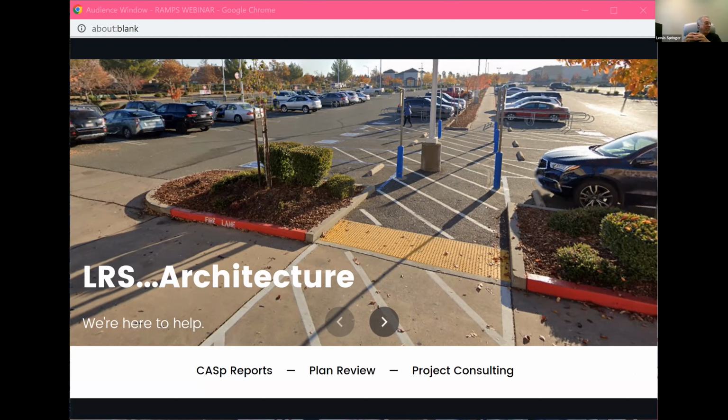But our first question is, could you please repeat the difference between blended transition and curb ramp? Okay, so what I like to look at is that a blended transition is any connection that's less than 5%. So if it looks like a curb ramp, but it only slopes at 4.5%, I kind of look at it as a blended transition.